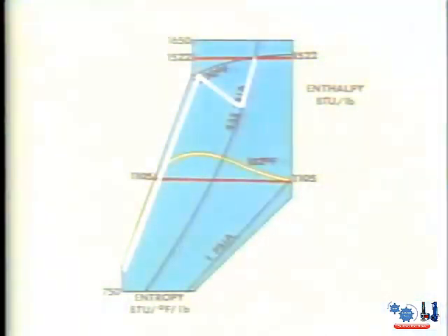After the steam passes through the IP and LP sections of the turbine, it is exhausted into the condenser at 1 psia and 102 degrees Fahrenheit. To find out how much energy is removed from the steam as it passes through the IP and LP sections, we first plot the conditions 1 psia and 102 degrees and find the difference in enthalpy between the outlet conditions of the reheater and the outlet conditions of the LP turbine.